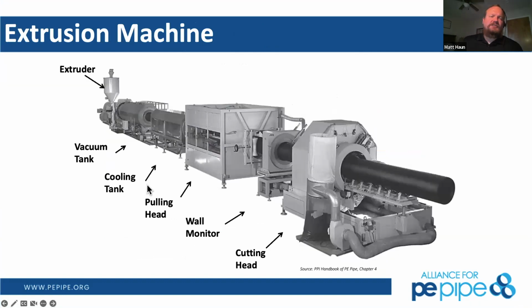Next slide. When we get it at the plant, we distribute it to our various extrusion lines. I like to talk about the process of extrusion real quick, because it gives you a frame set for how the pipe is made and what kind of benefits that'll have down the line. It comes out of an extruder as a melted extrudate that goes into a die. This die takes the solid bar of molten extrudate and makes it hollow. From there, it goes into a vacuum tank, which is where we set the OD dimension, the outer diameter dimension of the pipe.